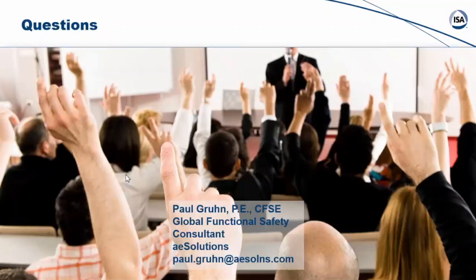Paul, this is related to something you mentioned earlier. What does the grandfather clause really mean, and what do I have to do to meet it? That used to be clause 1.y, the one thing we added back in 2004 that differentiated ISA 84 from 61511. Actually, then it was ISA 84 in parentheses, IEC 61511 mod for modified. We added one sentence. So what do you do about all the systems that you installed in the 80s and early 90s before any of these standards were available?